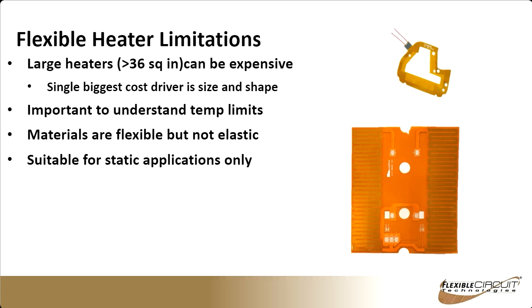aware of. If you have very, very large heaters, things that are over about 36 square inches, they can be expensive. I'm going to be getting into cost drivers here a little bit down the road. It's also important to understand the temperature limits of flex circuits. I'm also going to get into that. The materials we use are typically polyimide film, and those are very flexible, but they're not elastic. So it's important to keep in mind that they don't stretch.